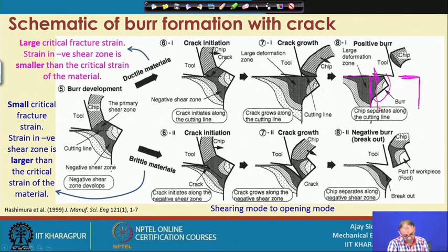But the problem is here, our requirement was this much, correct. So even if you apply some deburring operation, you can remove this much only, but there is no material at this location. So even if you apply deburring, this is what you will get, correct. So this is dimensionally inaccurate.